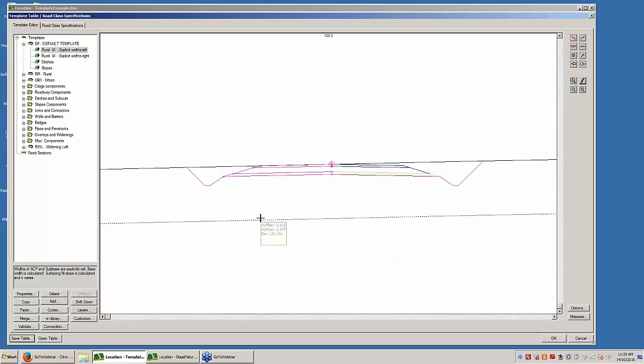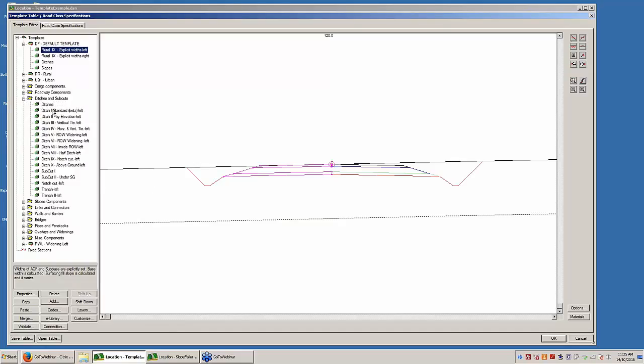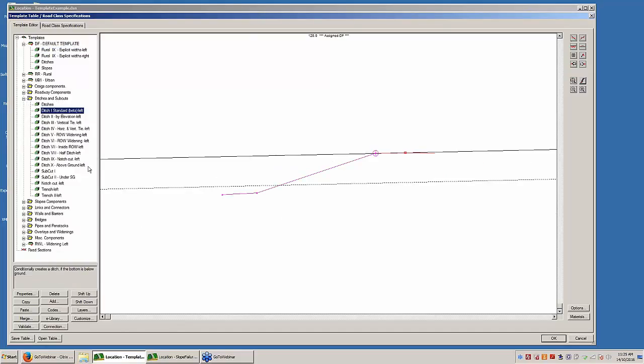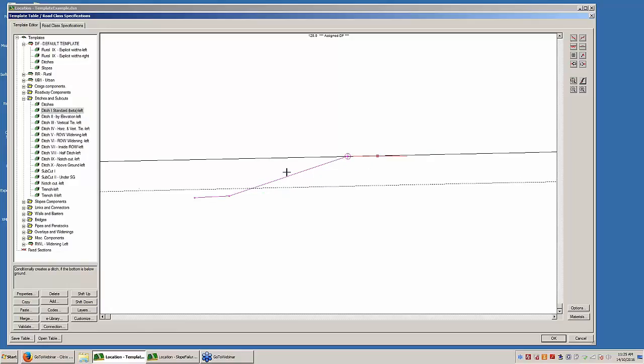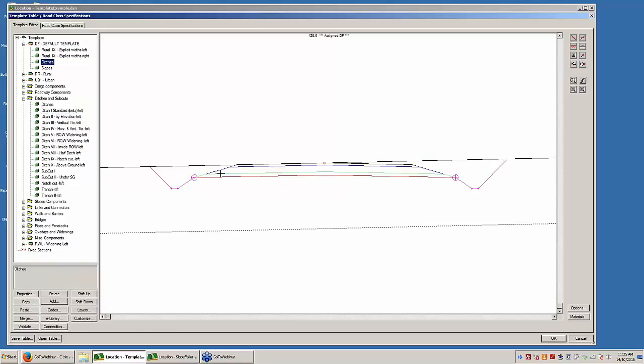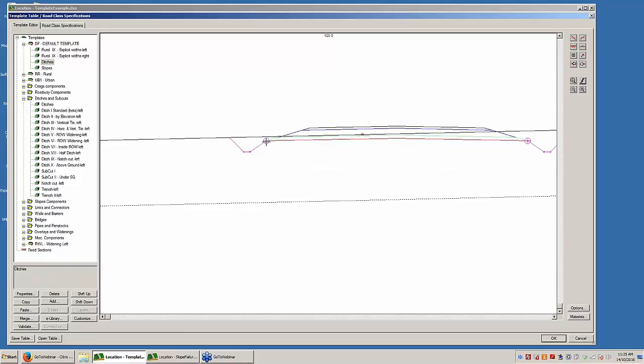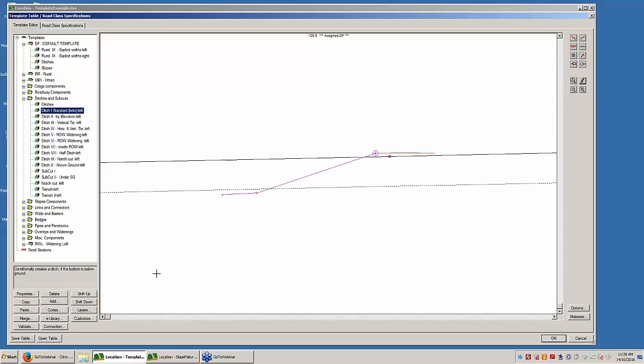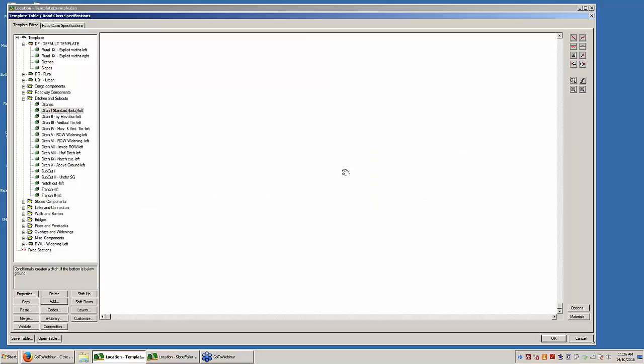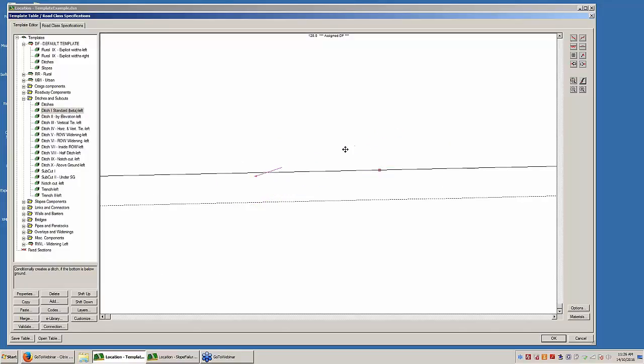So quickly, let's look at a couple of components that are interesting. I can't look at them all. There's quite a few, and there's lots to consider. Let's look at the ditch component. I complained a bit that this ditch component here is not good in a lot of situations because it pops a ditch in only when you're in cut at that point. What might make more sense is to look at this point on the ditch and say, if that point's underground, then I'll create the ditch. So that's what our standard ditch library component does. You see there, it disappears the minute I go above.